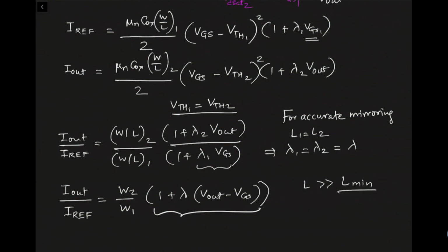So any technology, let's say you're using 1 micron technology, what that means, 1 micron CMOS technology means the minimum channel length of that device is going to be 1 micron. If you're using quarter micron technology, which is 0.25 micron technology, that means L is equal to 0.25 microns minimum. And what we have been using lately, the last chip that we did in our lab was 65 nanometer, which means that the minimum channel length is 65 nanometer.